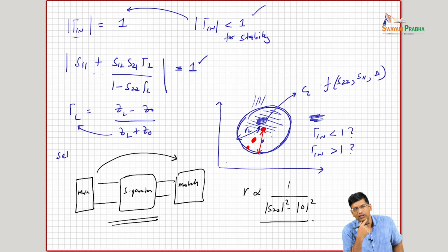Borderline, yes, but usually in IC design you try to get KF greater than 1, because you're always worried about parasitic coupling scenarios that you're not confident in. Typically, while you may know the drive impedance that you have when you are starting to design a block, you do not know what the interconnect between your block and the other block is going to look like.